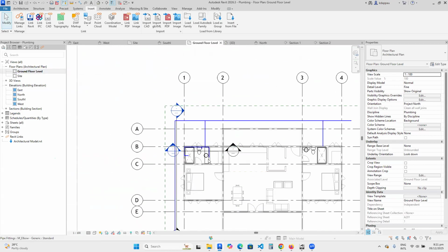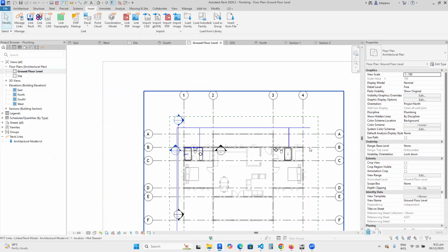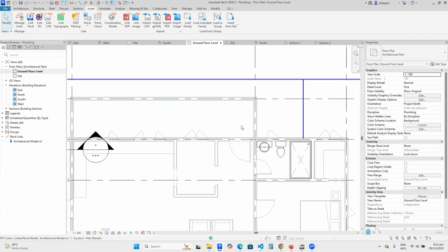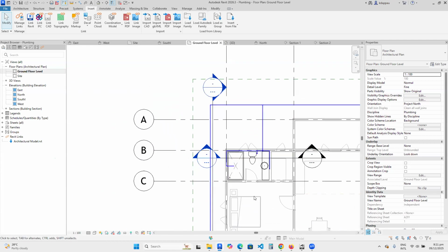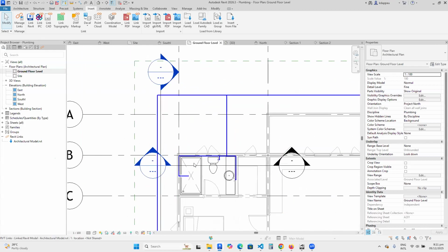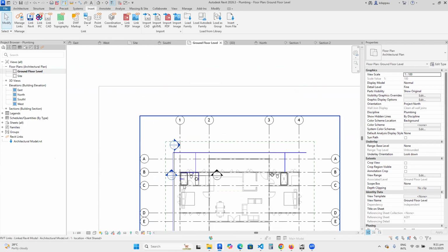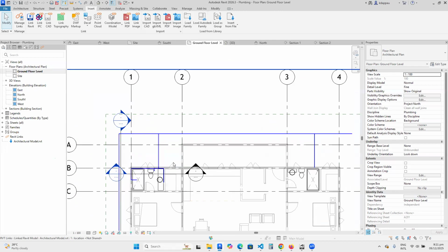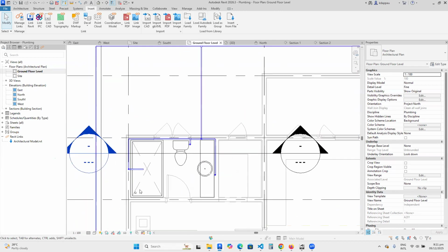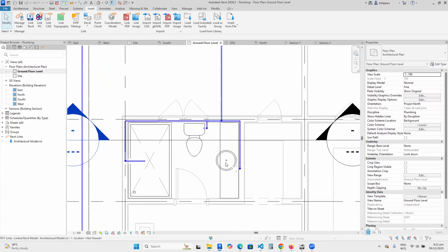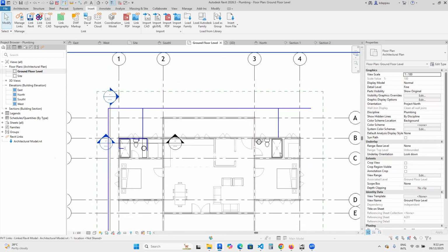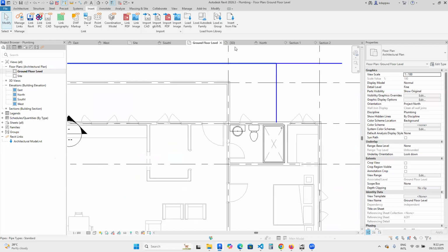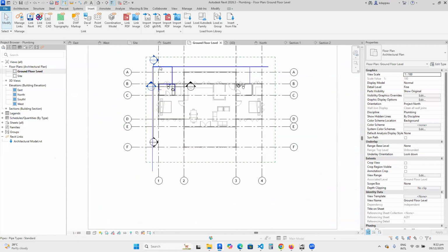Now, you see, when you are doing design, you should take note of some few things. There's a plumbing arrangement here. Then there's also a plumbing arrangement here. So you must design your waste pipe in such a way that they can easily be connected. You understand? So instead of me starting from here, I'll connect this one to this, bring it outside here. Connect this one to this, and then bring it outside here, so the two can be connected.